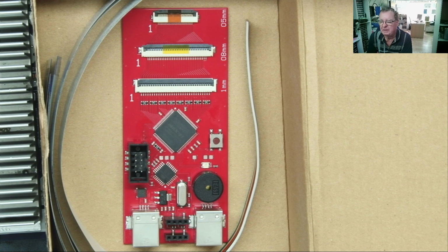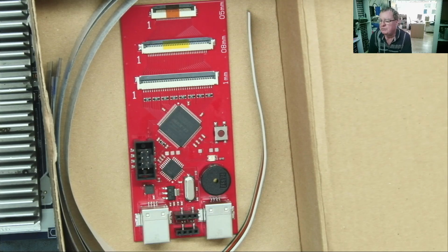It's more like having bad CMOS settings, really, like resetting the CMOS on the motherboard. You're not reprogramming it, it's just corrupted settings that stops the thing from booting. That's what this thing is for, by the way. One of the uses is to actually program EC chips in laptops, which it does via the keyboard connector.